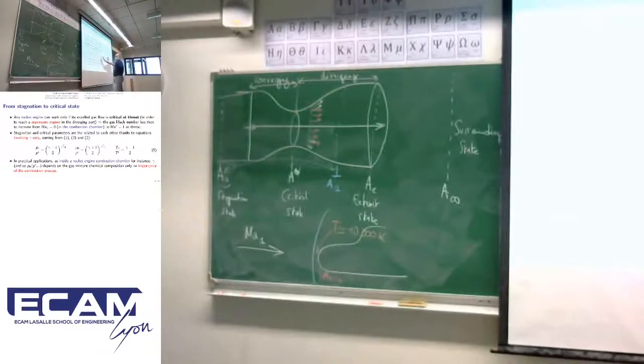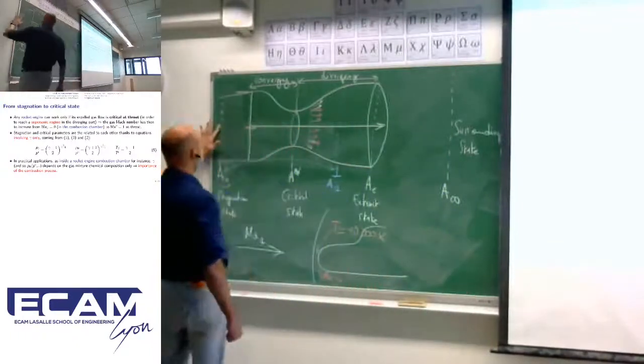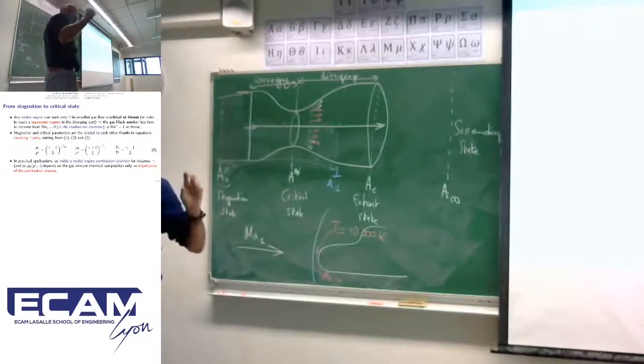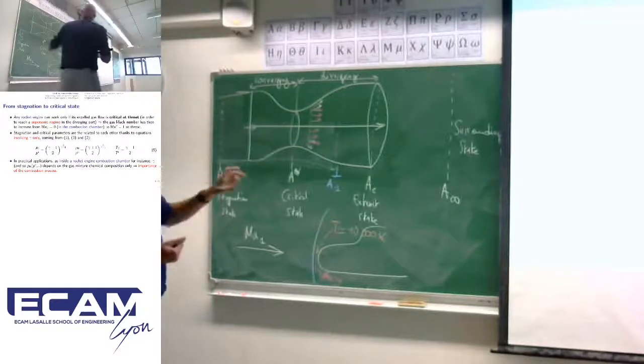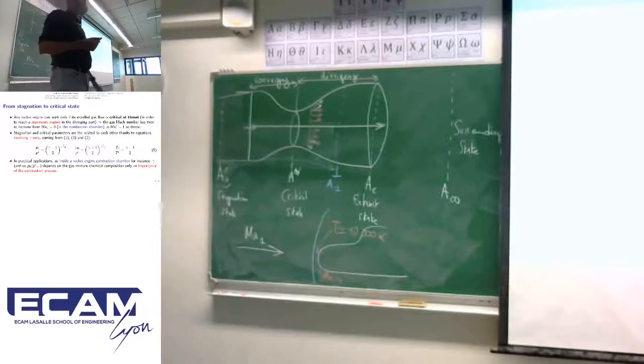And obviously, we have exactly the same relation for density, which is not so important. For temperature, it is, because temperature inside the stagnation state specifically is related to the temperature of the combustion, and we will do some calculation. It's called adiabatic flame temperature, just in order to have some order of magnitude. What happens, for example, when I mix some oxygen with some hydrogen, what is the level of temperature I can hope to reach inside the combustion chamber in order to just create this thrust effect, this nozzle effect?